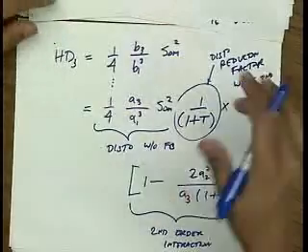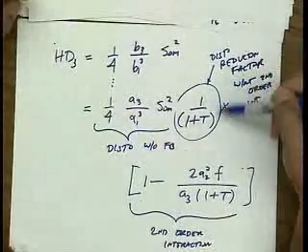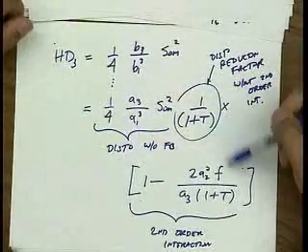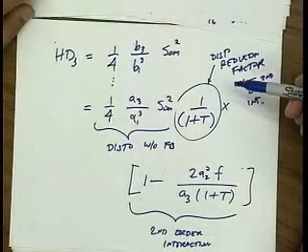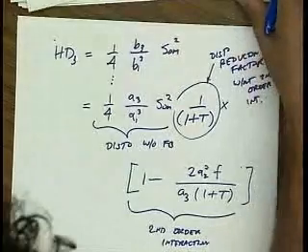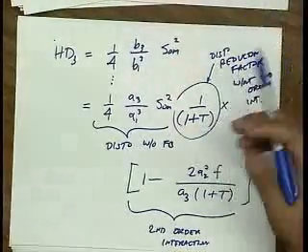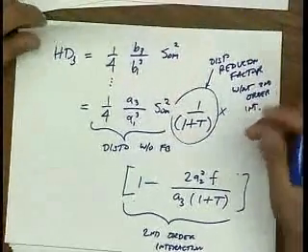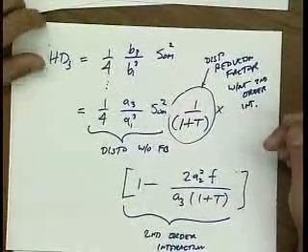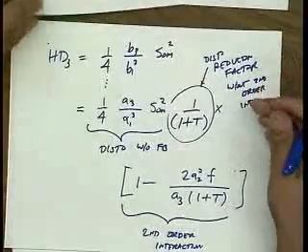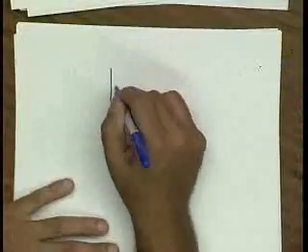So what's happening is that the action of the feedback certainly reduces the third harmonic, but it also generates an additional third harmonic. Now just to give you guys a little bit of intuition, the reason why feedback reduces distortion in the first place is, if we think about it in terms of an op-amp, right?